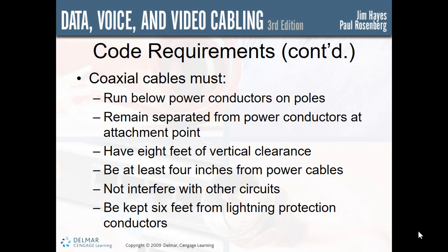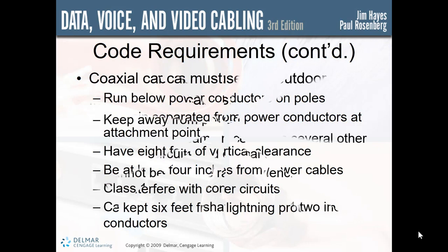They have an 8-foot vertical clearance, which means your trucks won't hit them. They must be at least 4 inches from power cables and not interfere with other circuits, and be kept 6 feet from lightning protection conductors.